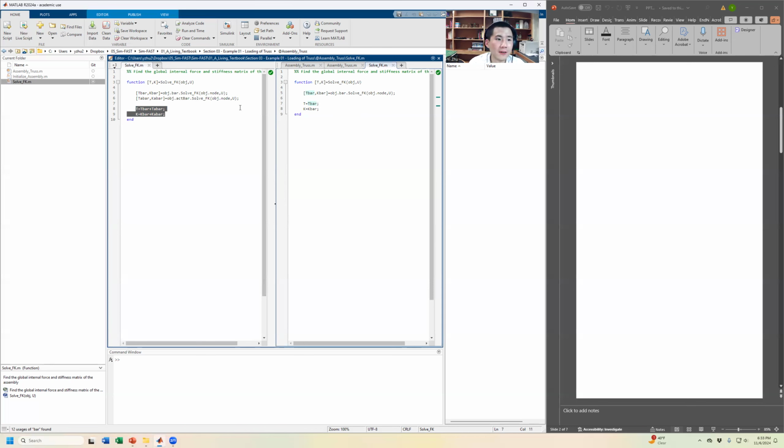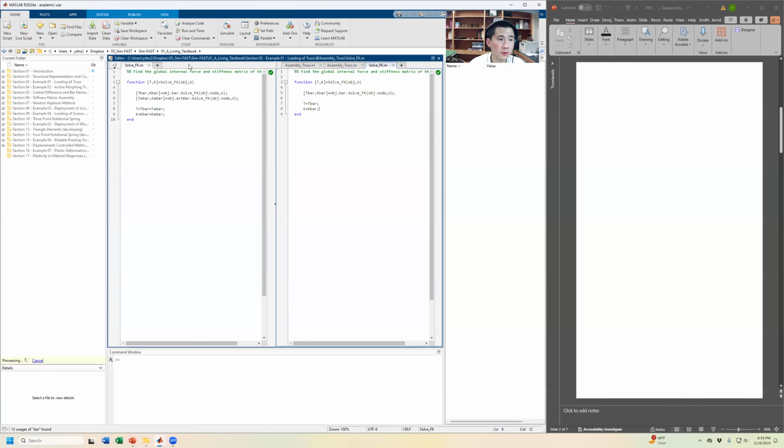That makes sense. So what this function is doing is basically for each type of the element, you solve their force and stiffness. So force vector and stiffness matrix, and it sums them to get a resulting total global force and global matrix. So in this situation where we only have one element, this is just one indexes. So that's something if you want to cook up your own assembly, you need to know how to do using these codes. So I would encourage you as we keep moving, we will see a lot more examples.